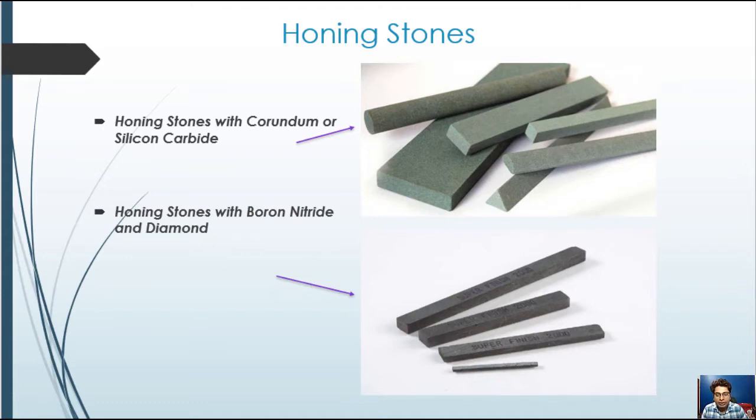The honing tools with conventional abrasive grains receive their desired form through mechanical material removal. Since narrow honing stones adjust themselves to the workpiece to be processed very quickly during their first use, a separate profiling process is rarely necessary. Only when machining holes with very small diameters, the honing tool must be rounded with leveling sleeves made of hardened steel. Honing stones which are either new or blunted through use must be resharpened.